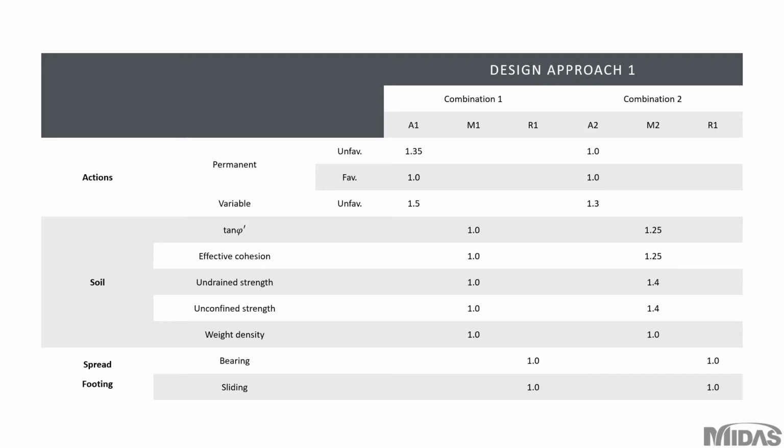And the partial factor values for actions will be multiplied by the original load, and the soil strength will be decreased when you apply the partial factor compared with the original materials. So I guess you will get a more conservative result compared with the original result, right?